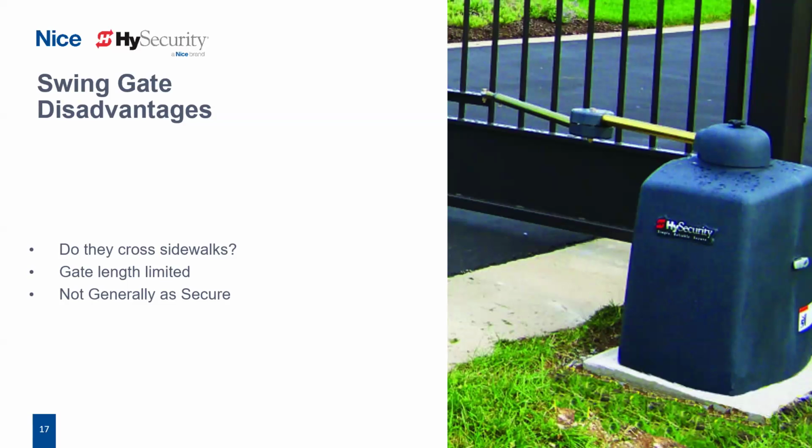Also, we want to make sure that we never have a solid panel. A solid swing gate panel is going to become a sail in the wind, and all operators might have an issue trying to open them in the wind. And these are generally not as secure as slide gates.